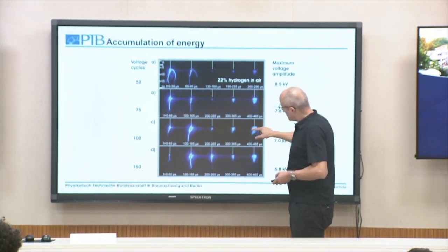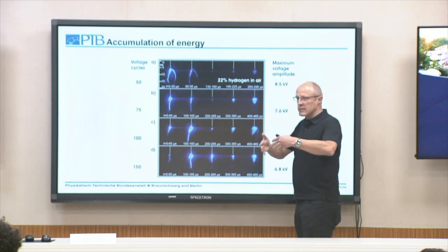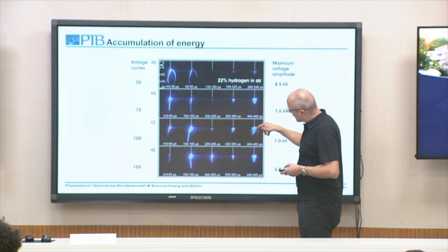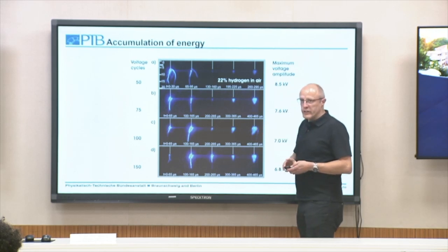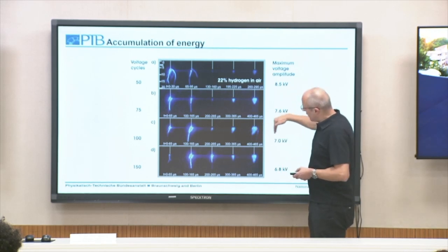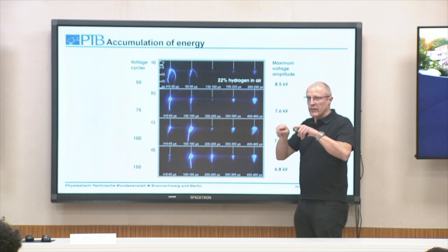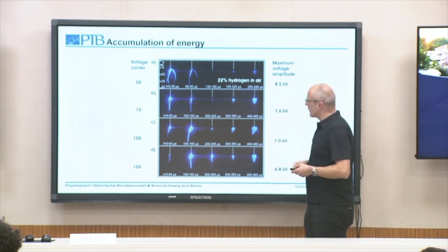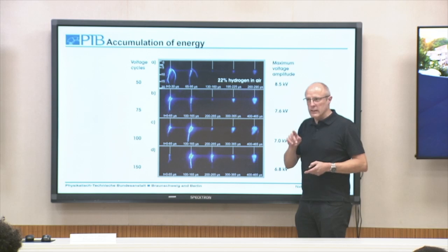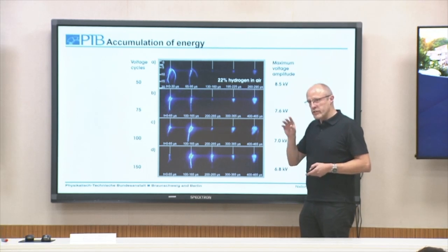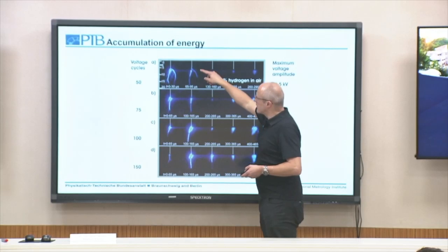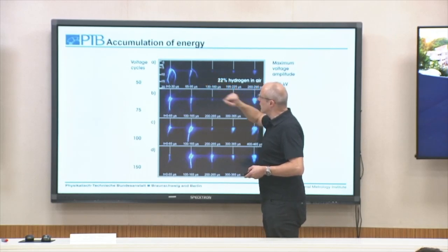And so finally here the flame front starts to move outside into the unburned region. So, if we would continue this, we would see more or less a spherical flame moving in the unburned mixture. So again, this is not a classical spark ignition where the high temperature dominates the ignition. Here we have this so-called non-equilibrium plasma.